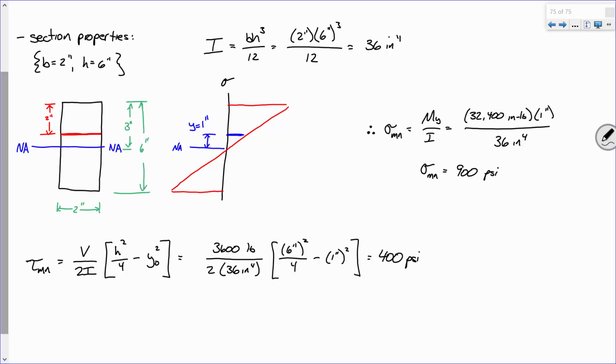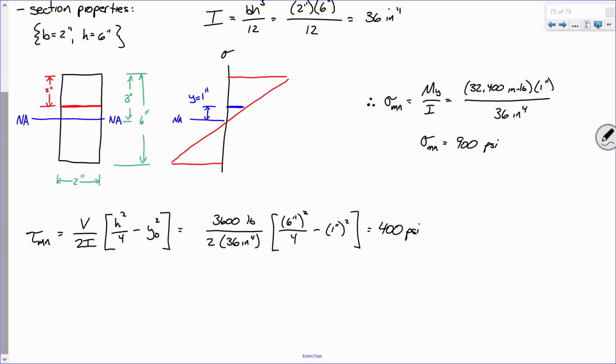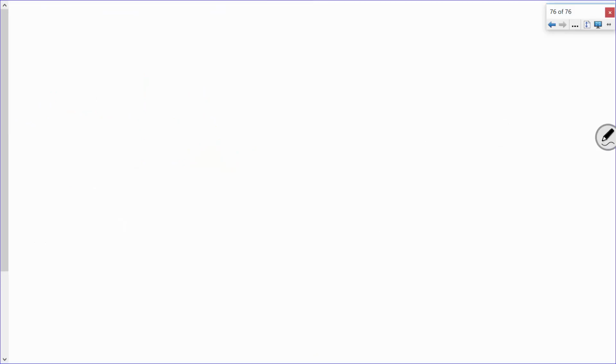Everybody okay with that? All right. If you're okay with that, then here's what I propose. All right, can I go on to the next panel? Now we need to do a Mohr circle analysis. Although instead of drawing the circle, we can just use the formulas. Now, in order to draw a Mohr circle, we need a sigma x, a sigma y, and a tau xy. Okay. Now, what was our shear stress? 400 psi.